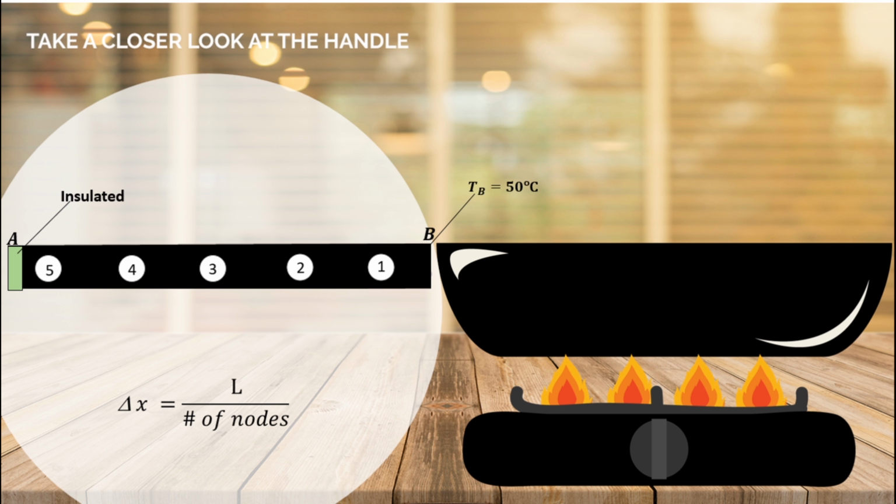The more points we take, the smaller the grid size we get. It usually gives us a smoother result. As you can see, the distance between the point and the boundary is delta x over 2, and the distance between 2 points is delta x. There are some other definitions we need to get familiar with before we move on.